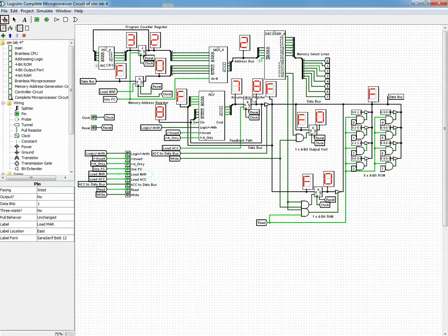If I tick the clock directly, the 8, which comes here, will be passed to the accumulator register. So this is why I need the load ACC. I need to set it to 0, otherwise this 8 will be lost. So that's why I set it to 0.